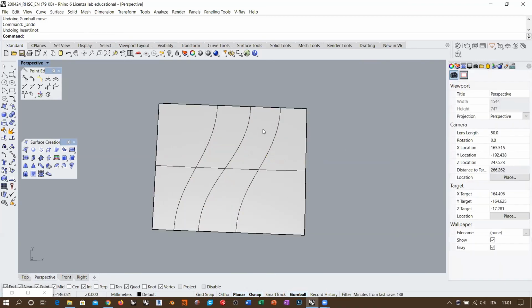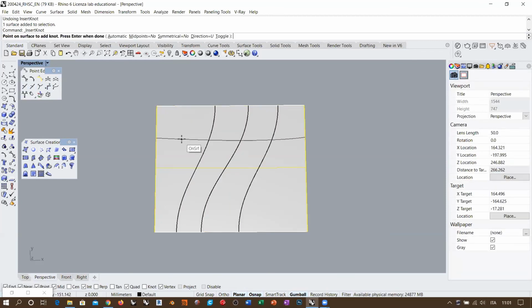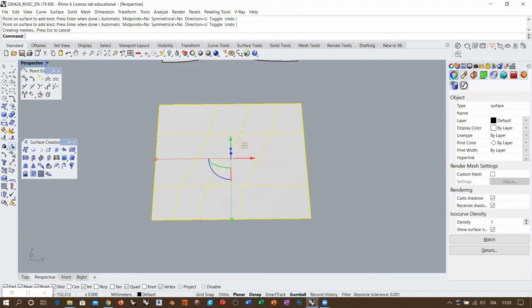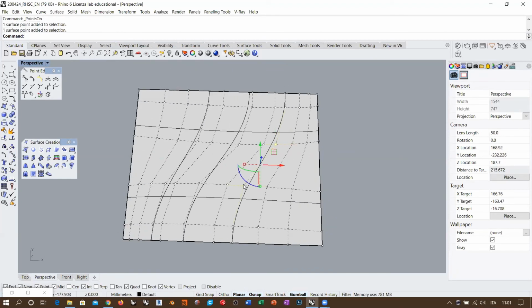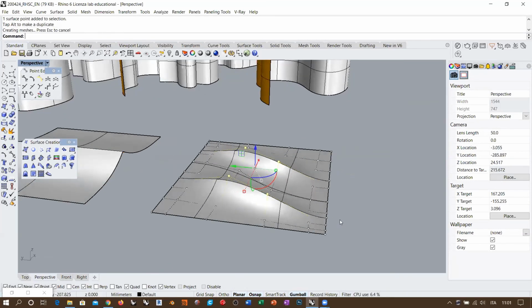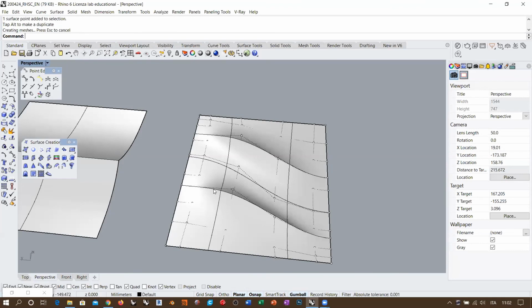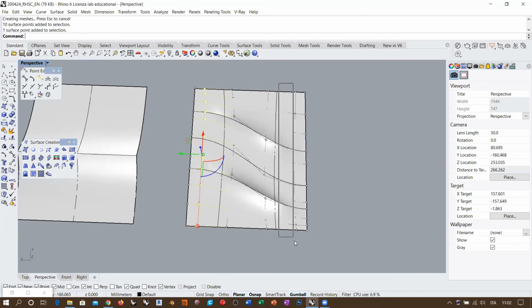So, for example, if I undo this knot line, and I repeat it, and I create more towards the inside, like here, and activate the control points. Now, if I take the inner control points here, and also this one and this one, I can still produce creases, but these creases tend to die sooner than in the previous case, okay? Because my control points are more separated from the corresponding edges. So basically what I'm doing by adding this knot line is creating this line of control points here, and also this line of control points here.